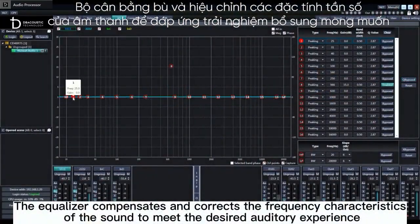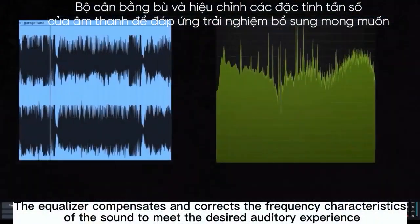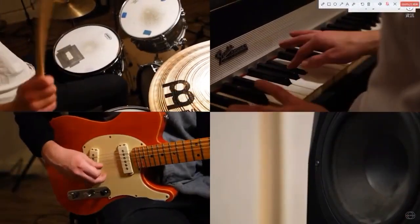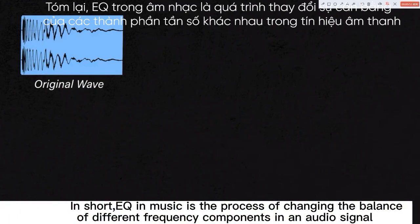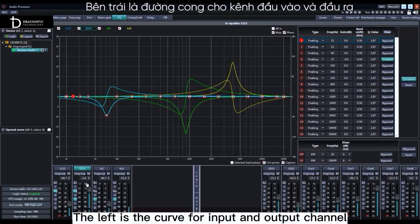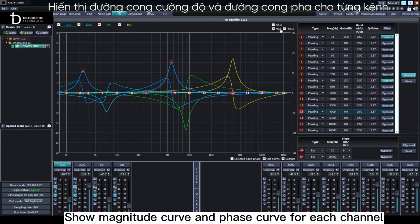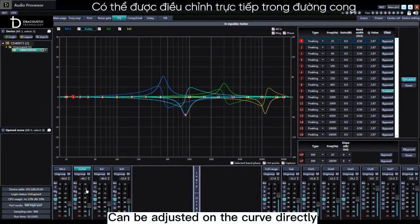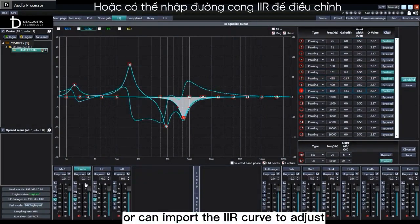The equalizer compensates and corrects the frequency characteristics of the sound to meet the desired auditory experience. In short, EQ in music is the process of changing the balance of different frequency components in an audio signal. The left is the curve for input and output channel. Show magnitude curve and phase curve for each channel. The right side is the equalization parameter setting area. Can be adjusted on the curve directly, or can import the IR curve to adjust.